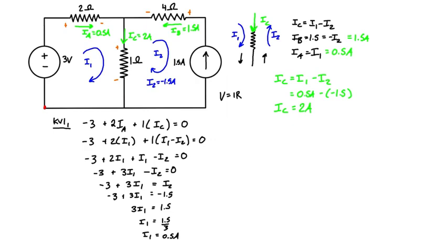Depending on what the question is asking you, like finding the power dissipation in the resistors, or often it's just asking you to find the mesh currents themselves, which are the blue lines, or the branch currents, which are the green ones, depending on the structure of what you're being asked for, just apply Ohm's law and then go on with that. So yeah, that's a quick introduction to mesh analysis.